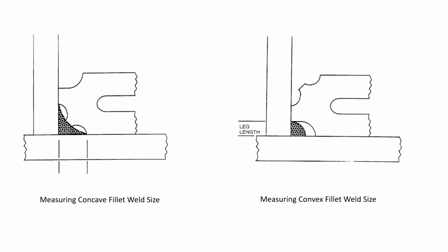We flip our fillet weld gauge over, and we measure both legs of the fillet weld and see if it meets the requirements. So right there on that blue one, we put that little prong down in there, and if it touches the fillet weld there on the left with the little blue arrow, we know that we've reached the requirement for that drawing or specification.